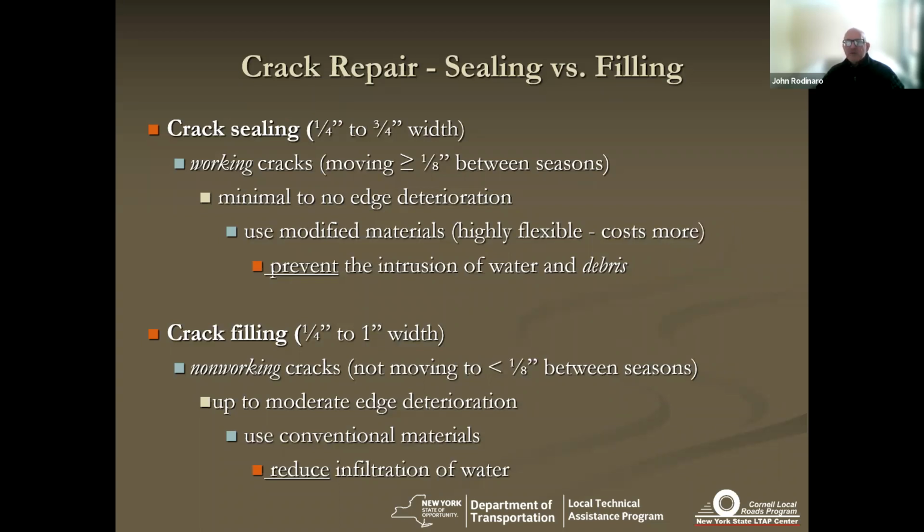Because as you probably all know, in the wintertime, that crack is wide open and you're getting a lot of road junk that's flowing with the water into that crack. Well, as that weather gets better and the temperature starts going up, that side of that crack is narrow, and that side of that crack is going to be pressing hard up against that debris. Well, the debris is breaking down, but so is the side of that crack, and that's going to greatly accelerate the deterioration of and distress on that pavement.